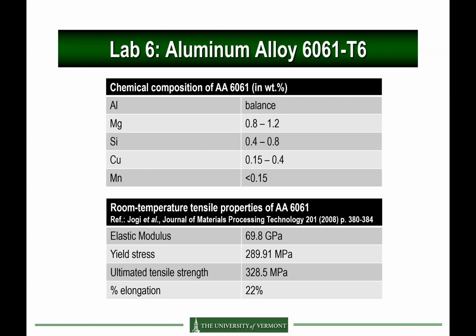And their performance in fatigue is quite good. So the composition is aluminum and magnesium, and the other elements are just there for microstructure. Silicon also contributes to the high temperature properties of the material. By high temperature, I mean intermediate temperature, something on the order of maybe 100 or 200 degrees C. Okay, but nothing very high. And the magnesium is usually used as a way to maintain or keep the microstructure constant.